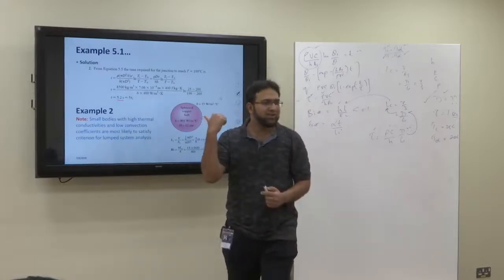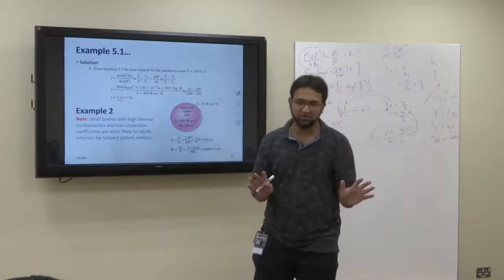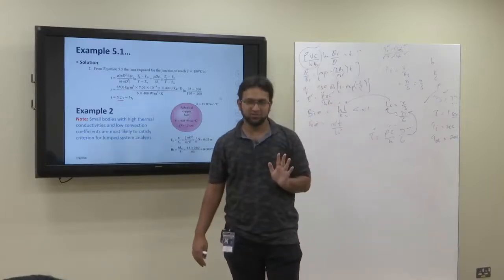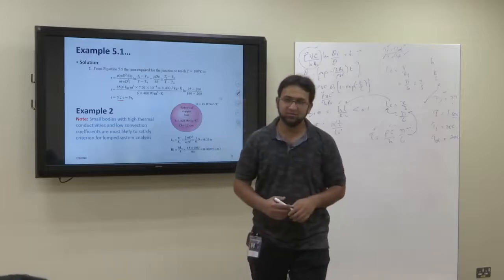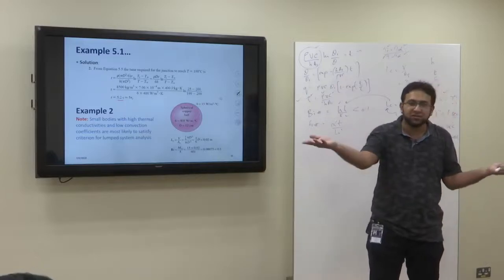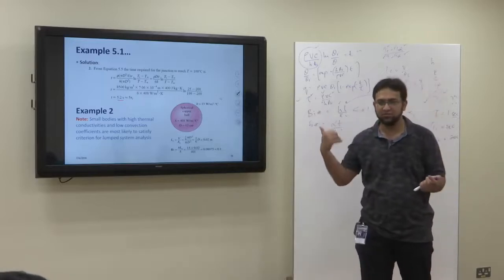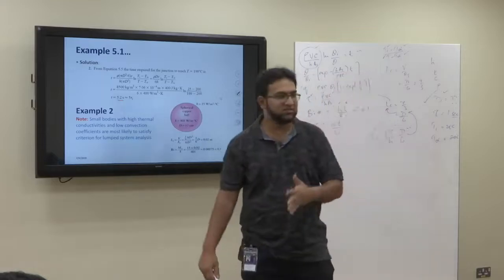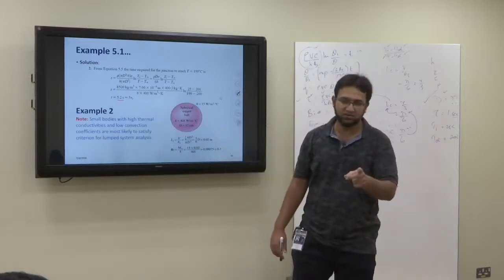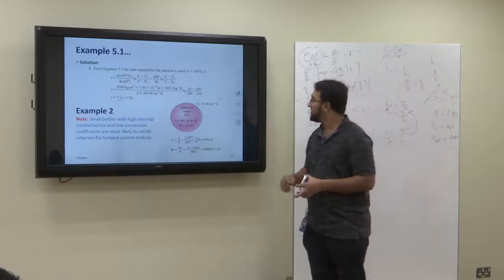Imagine it. Because we are finding the time, 5.2 seconds means reaching 199, which means approximately reaching 200. Yeah, it will give you 200. But if you wait till 6 seconds, you will get the right temperature. Okay? If I proceed more, it will not exceed. Obviously, the maximum temperature it can reach is T infinity. That's the temperature of the gas stream, and that is the temperature it will give. Okay? So you wait till 6 seconds, 10 seconds, 15 seconds, it will give you 200. But if you wait less than 5 seconds, it will give you a wrong temperature. Is it clear?